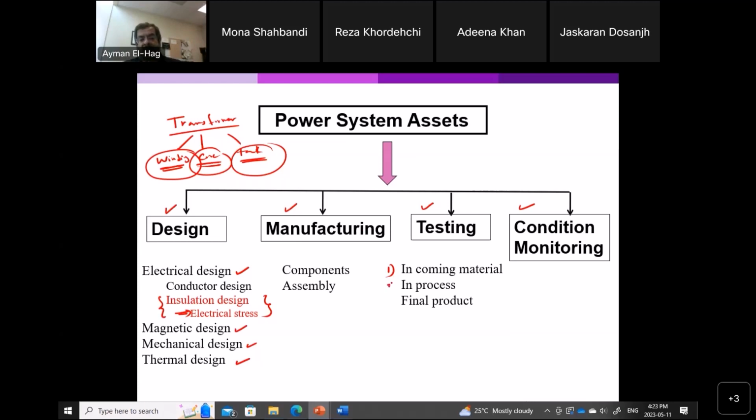Then in process, as we are going through the different stages of the transformers, you want to do different tests, mainly your technical dimensions, so that when you reach the assembly stage, there is no big issue. But also, one of the tests that we do in process is the Megger test. Because in the manufacturing of the transformer, when we connect the winding with the core, to prevent any moisture, we put the transformer in an oven to get rid of the moisture. To make sure that this process was effective, we measure the electrical insulation. So that is a high voltage job.